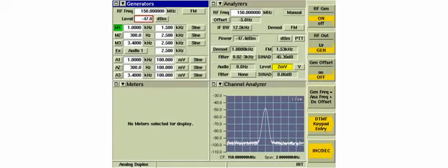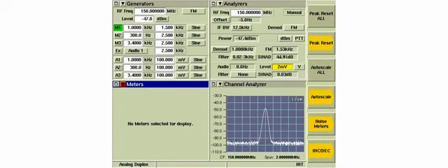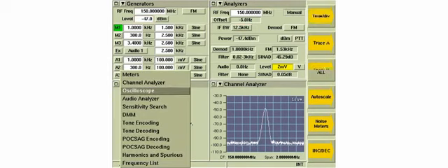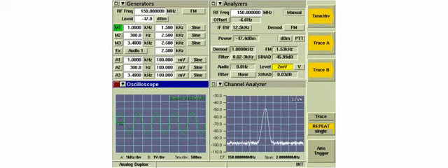The 3920 oscilloscope is selectable from any analog or digital test system. We will use the analog duplex test system for this example. The oscilloscope can be selected from any tile containing the drop-down arrow. We will use the meters tile for this example. With the oscilloscope tile highlighted, control soft keys will appear on the right.